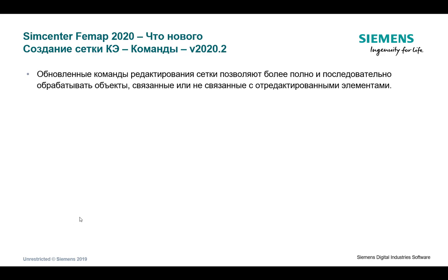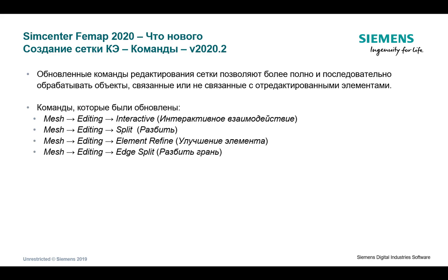Another thing we did for version 2020.2 was update the various commands on the mesh editing menu to make them more consistent with one another. These commands, mesh editing interactive, mesh editing split, mesh editing element refine, and mesh editing edge split, all behaved a little differently, mostly because they were added to Femap at different times in completely different versions, and they just were